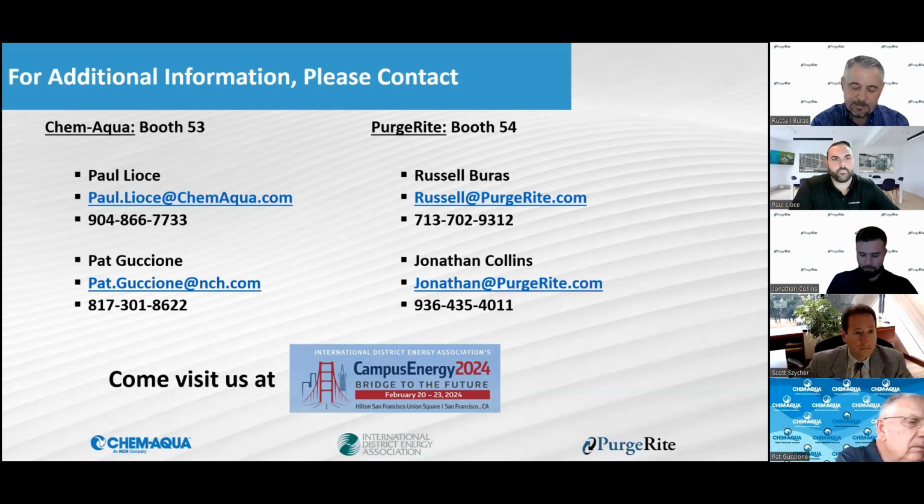Now, when you're circulating, and I call them the soaps, but ChemAqua will have their nomenclature. But when you're doing the cleaners and those types of things, and y'all can correct me if I'm wrong on this technically, basically you're stripping iron off the metal, and you'll see the iron start climbing. And when you're trying to manage that iron, you're trying to get this done as quick as possible. You can bring in makeup water and discharge that too to get your parts per million down to where you need it to be, which is typically less than 1. And some people want it a lot less than that. So that's where the water comes into play.